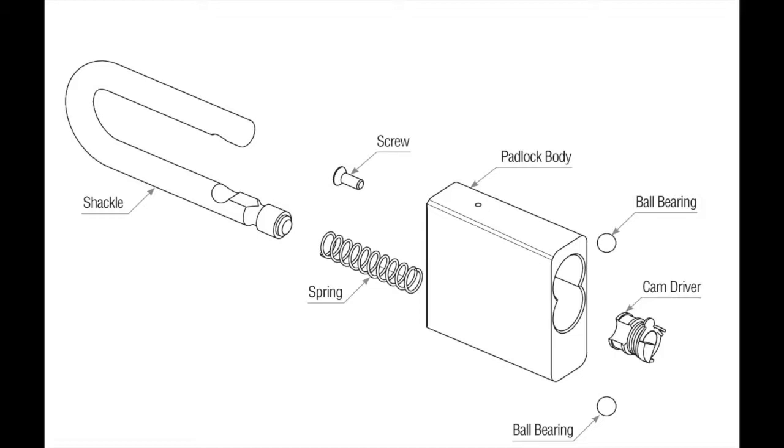So in this case, we chose a 1 centimeter diameter. Also, if the lock is larger, it costs more to manufacture, so we took that into consideration as well. As a length, we chose 15 centimeters, as we don't want to make it too long, as more length gives more room for the shackle to be tampered with. And the shackle is notched at the ends to lock in place with the body of the lock.